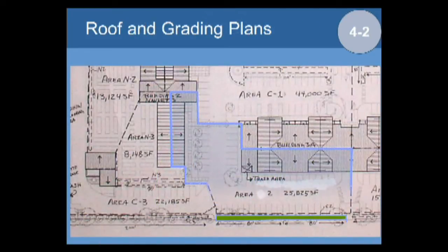when you consider a DMA and you're drawing it, pretty much the way this is going to work is that it's always going to follow roof ridges and then the grade breaks and the pavement around, divide your site up into separate areas pretty naturally. And then in your design, what you want to do is to try to make this distance between your drainage management area and your facility as short as possible, because particularly on a flat site, you need to worry about how much head that's going to take up if you have to be transporting water from one place to another.